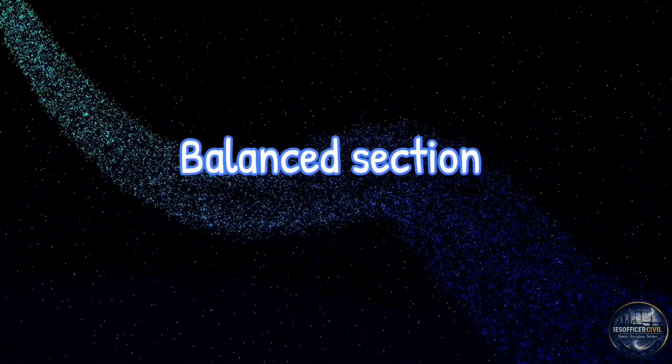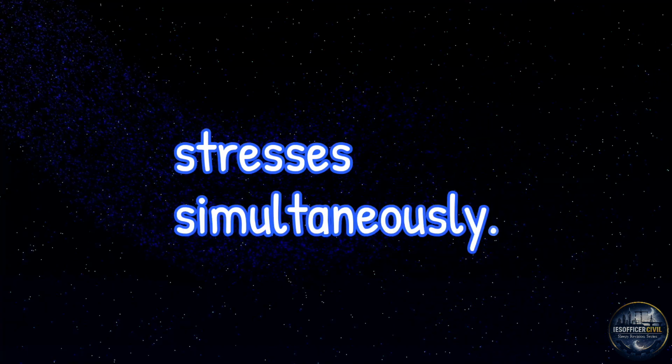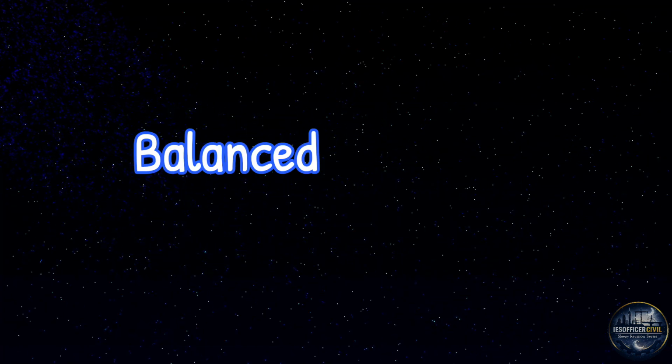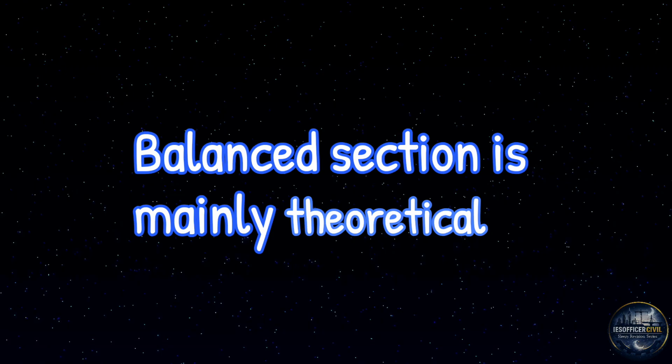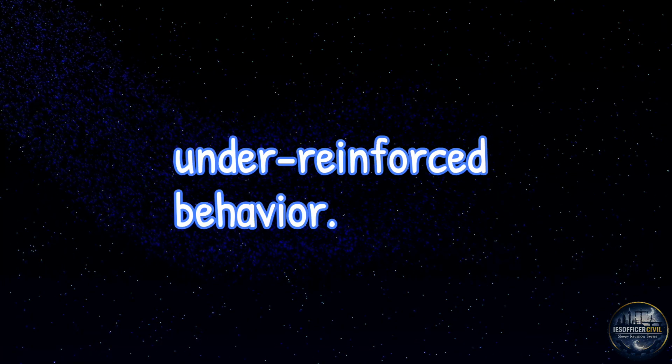Balanced section means steel and concrete reach permissible stresses simultaneously. Balanced section is mainly theoretical because practical design prefers under-reinforced behavior.